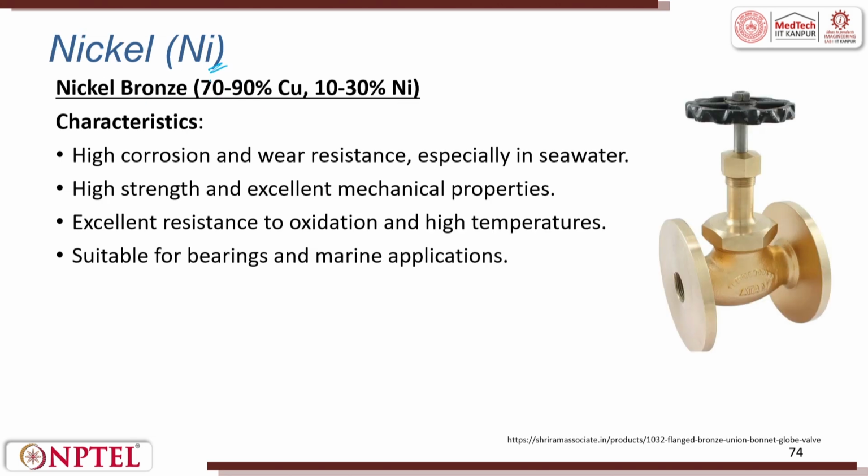Moving towards nickel, nickel bronze, which finds excellent application in marine fittings. Here it has high corrosion and wear resistance, especially in seawater. Suppose a water tank, along the coast, they always have these types of valves which are made out of nickel bronze. High strength and excellent mechanical properties are there. Excellent resistance to oxidation and high temperature. Suitable for bearings as well as marine applications. In marine, we always use nickel bronze as the material.